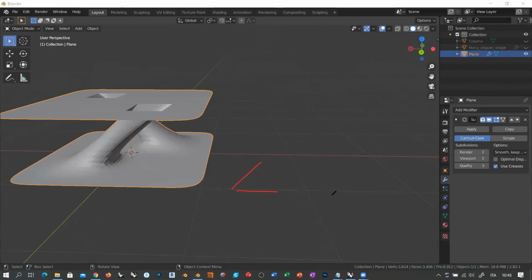I created a horizontal plane, and despite the subdivisions and everything, this plane had the positive normal like this, okay? And then I duplicated this vertically, and then I had another horizontal plane at this height with its positive normal like this, okay? So when I connect with these diagonal faces, these to these,